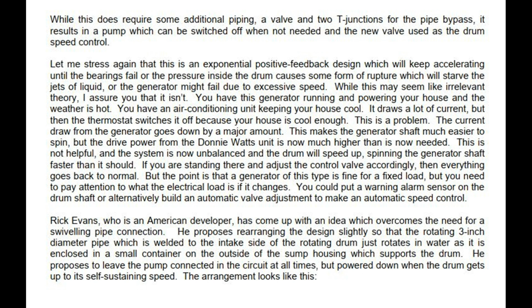This is not helpful, and the system is now unbalanced and the drum will speed up, spinning the generator shaft faster than it should. If you are standing there and adjust the control valve accordingly, then everything goes back to normal. But the point is that a generator of this type is fine for a fixed load, but you need to pay attention to what the electrical load is if it changes. You could put a warning alarm sensor on the drum shaft or alternatively build an automatic valve adjustment to make an automatic speed control.